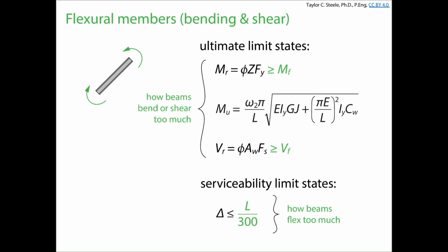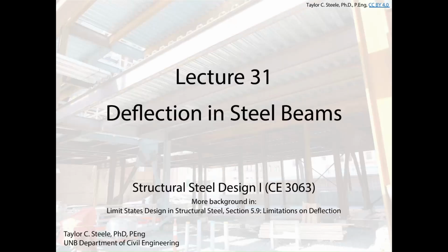And for the most part, I'm not really going to show you anything new today. I hope I'm not showing you anything new today. But I'm going to place the stuff that you already know in the context of steel design and the stuff that we've been talking about so far in this course. Okay, so today we're talking about deflection of steel beams. For the most part, deflection becomes an issue the longer the beam gets. And for the most part, because of the way we frame everything, they tend to be most critical for joists compared to girders in our structure.